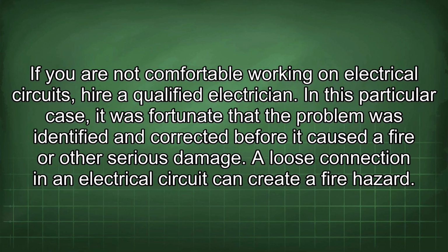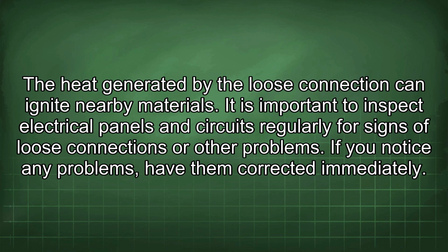In this particular case, it was fortunate that the problem was identified and corrected before it caused a fire or other serious damage. A loose connection in an electrical circuit can create a fire hazard. The heat generated by the loose connection can ignite nearby materials. It is important to inspect electrical panels and circuits regularly for signs of loose connections or other problems. If you notice any problems, have them corrected immediately.